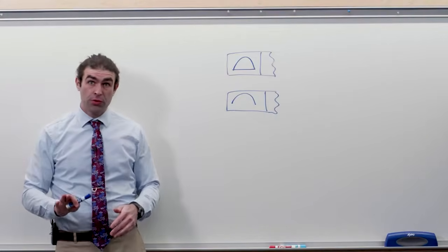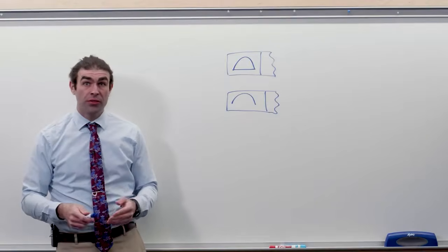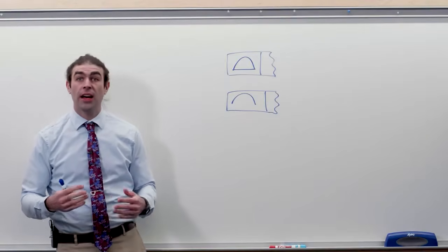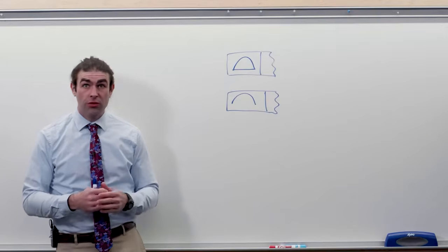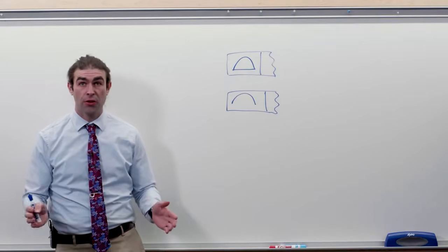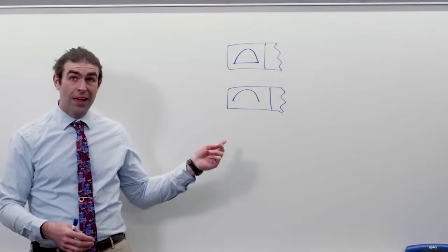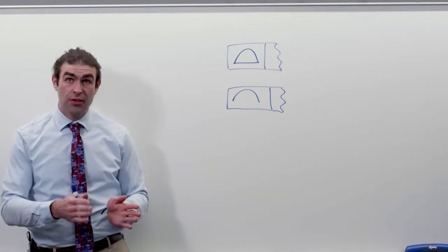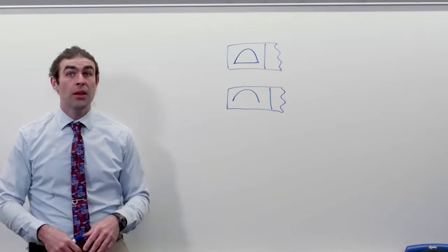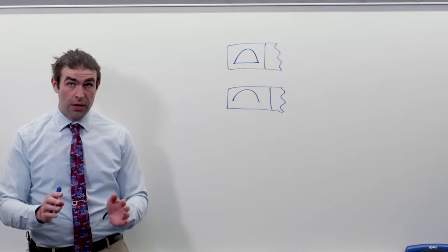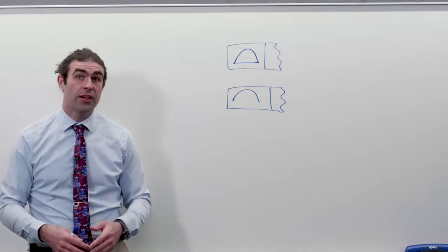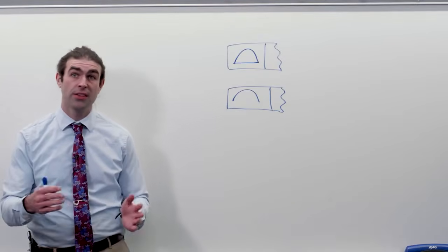Now the difference between them is that profile of a surface is a 3D tolerance. What that means is it controls an entire surface, whereas profile of a line only controls individual cross sections. So a good way to compare this to something we've already covered is the difference between flatness and straightness.